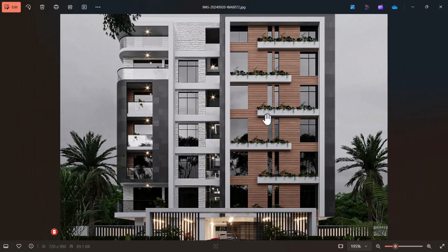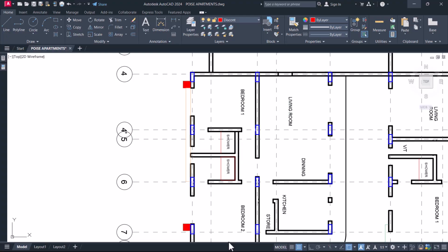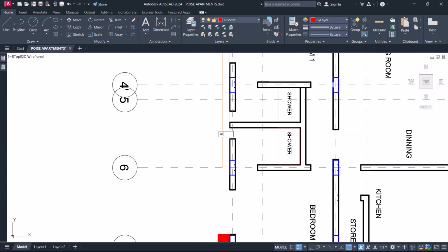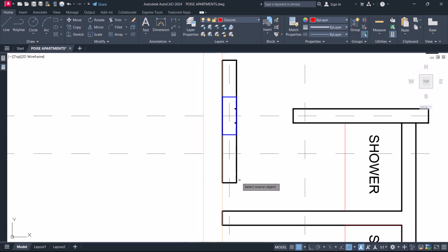This is the little extended part, so we exploit this option. It will also help us to have our columns not at the edge of the structure anymore. It will now be somewhere going to the mid of a slab, which is always advantageous to us during the design of a flat slab.